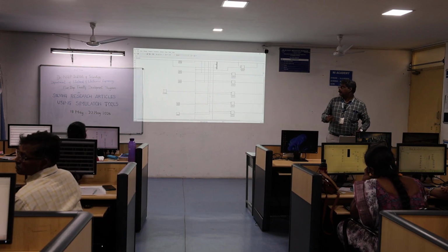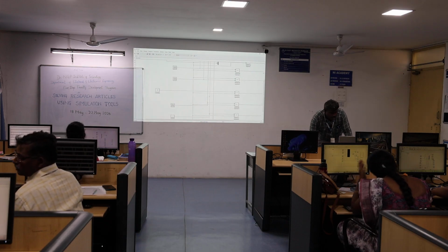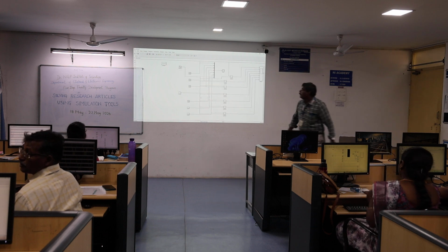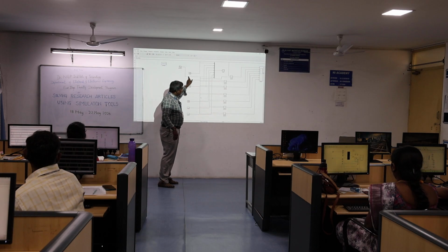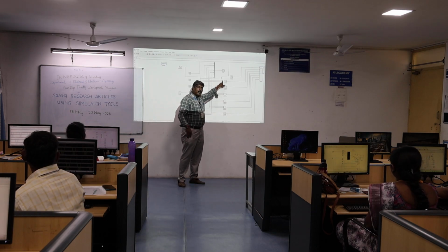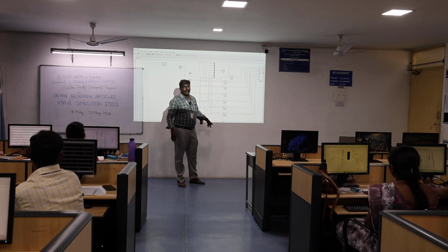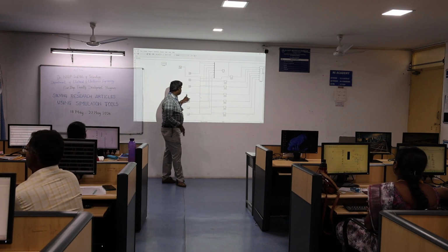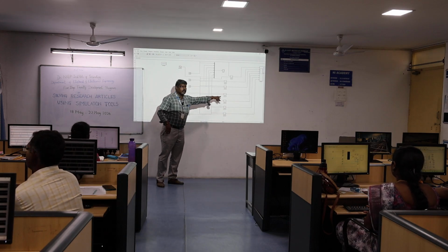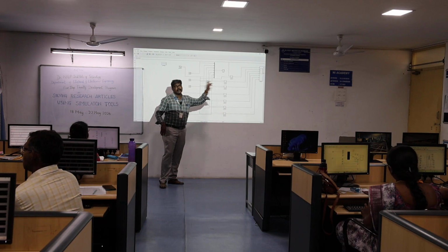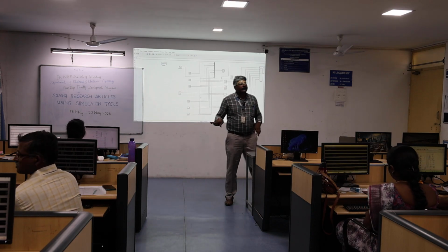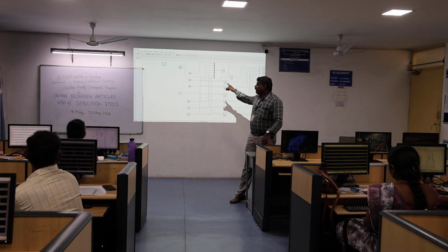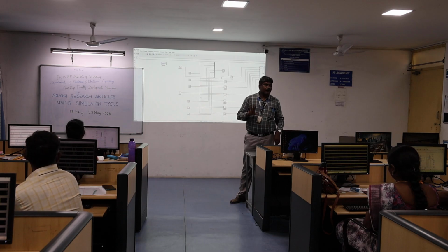Okay. So the output of the sine waveform is common to all the relational operators, one of the inputs, right? So the constant is also connected to one of the inputs. The remaining carrier signal is also connected as one of the inputs. So the common input for all the relational operators is the sine waveform. The sine waveform is the reference signal.